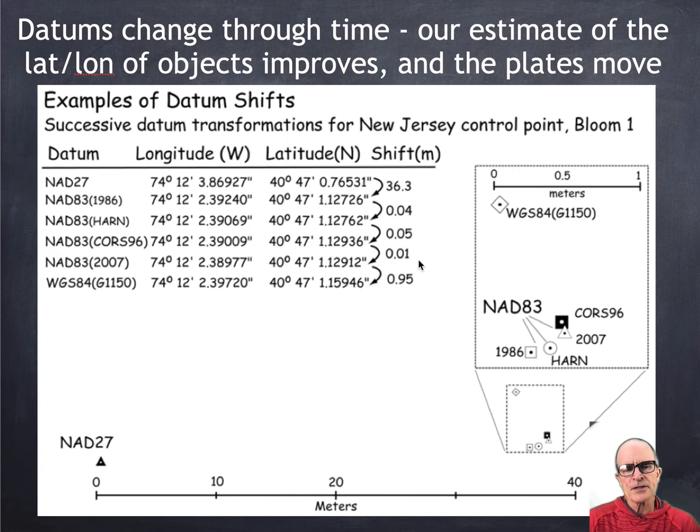There's a 3-foot offset between how the rest of the world measures location and how we do. Now, there's a bunch of complicated reasons, but the primary one is that we didn't want to change the locations too much within this NAD83 family to confuse the surveyors or make them have to go adjust their coordinates in the US because we switched datums.